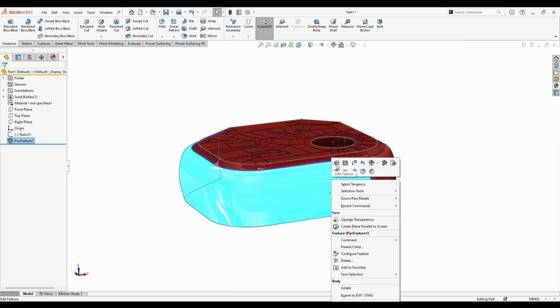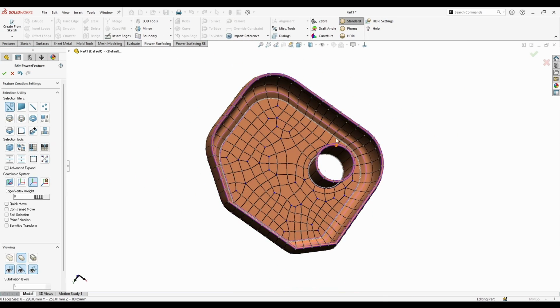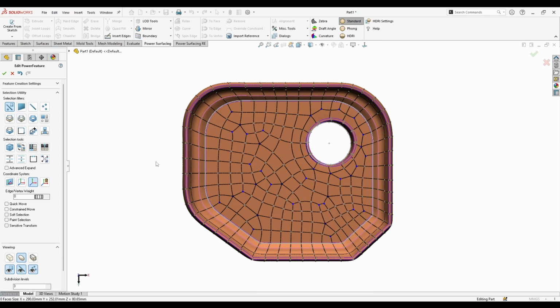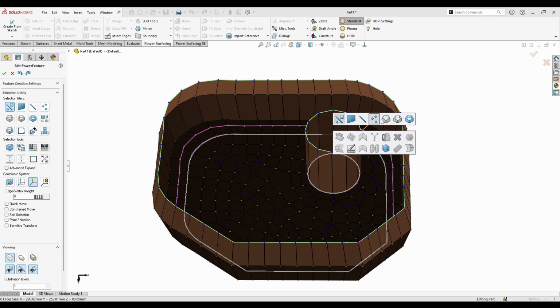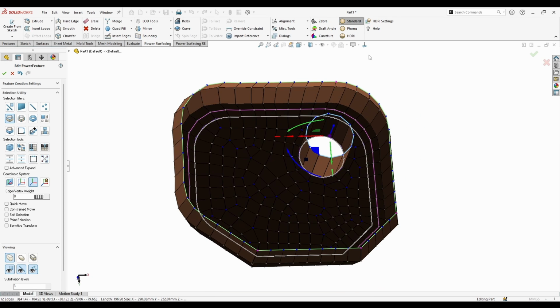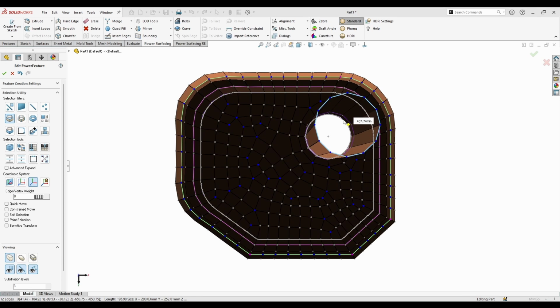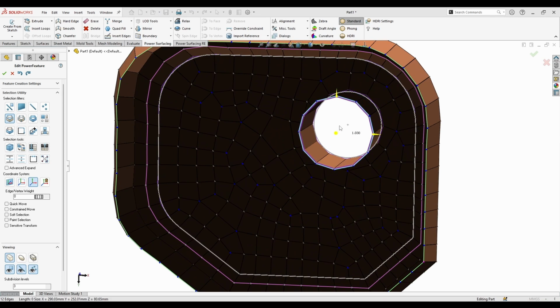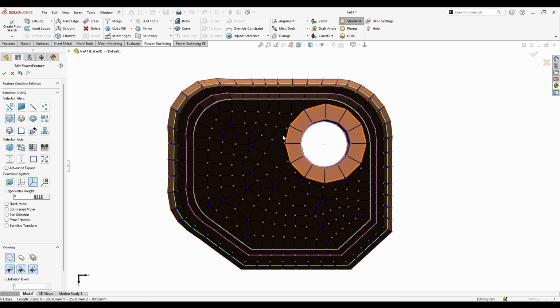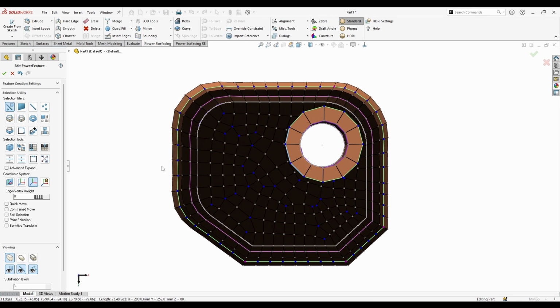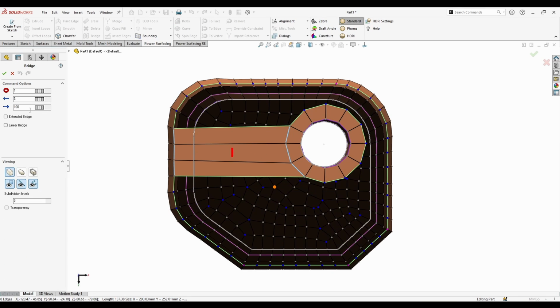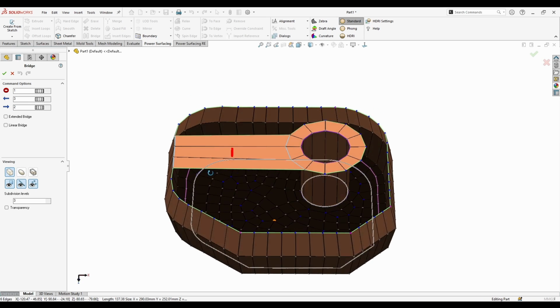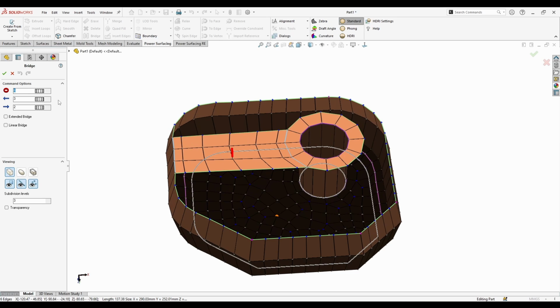Okay, and the other solution is to close this to make a solid. So let me show you how I can do this. At first, I'm going to hard edge this circle and bevel it, and easily select 3 edges from here and 3 edges from here, and make a bridge. Make this weight maybe 3 to be flat, and add more edges.